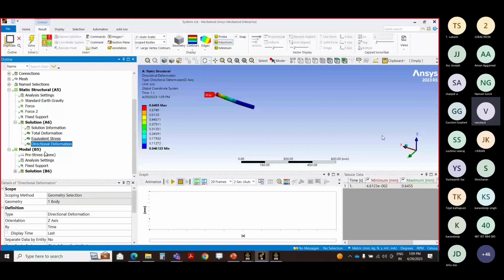And modal analysis is nothing but we need to find the natural frequency and mode shapes of the body. Whenever, after giving initial displacement, the frequency at which the body will be vibrating, we will be calling as a natural frequency. And natural frequency is nothing but root k by m. Okay, natural frequency is an inherent property, it depends on the body's properties, not on the external force.